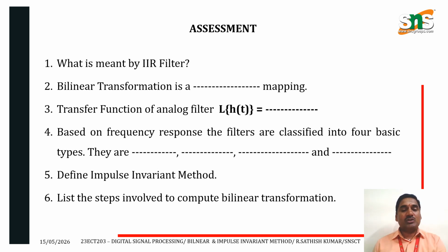List the steps involved to compute bilinear transformation. First we find out the analog transfer function, and we apply the transformation, whether it is bilinear or impulse invariant, and finally obtain the transfer function of the IIR filter.